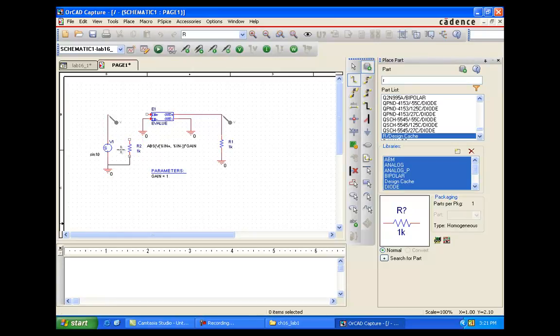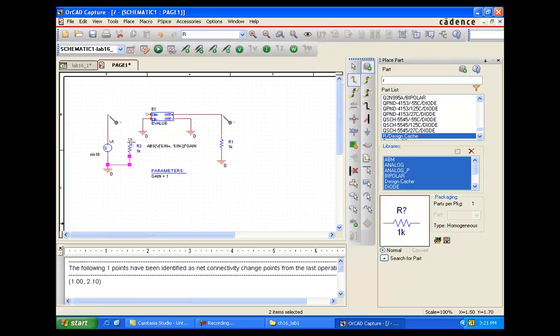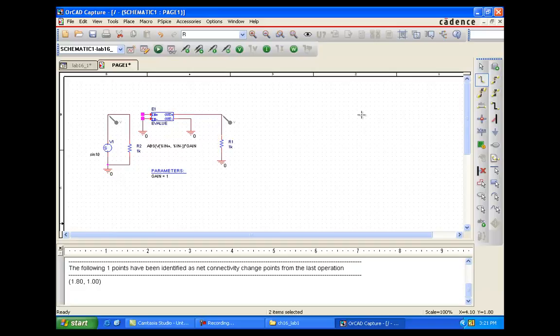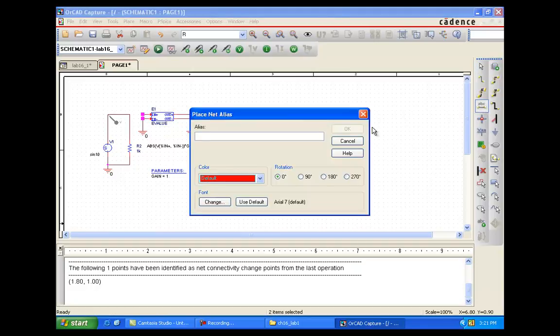In this example you will see that even though there is no input connected to the ABM symbol, it still functions. This is extremely useful if the output of the device is dependent upon more than just differential voltages. So that's the powerful tool of eval and G value. It gives more power and flexibility.